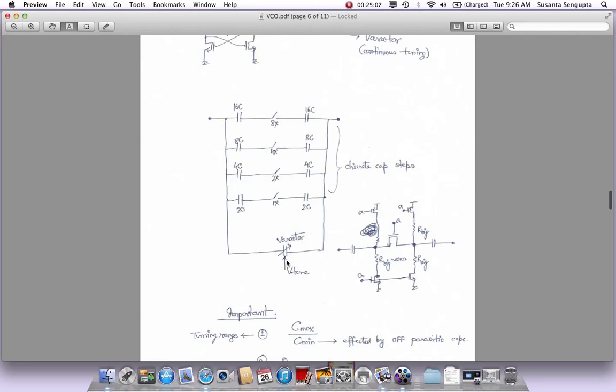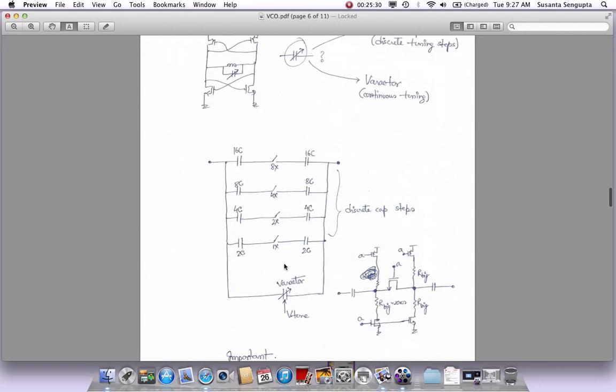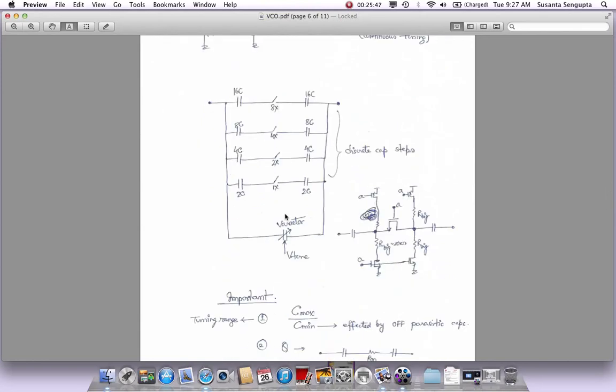Okay, so its input is a tuning voltage, and with that it will provide a continuous tuning within that discrete setting of the frequency that we have. So between discrete steps and continuous tuning, we can cover a pretty wide range of the VCO, and this is how we do tuning. It's not just continuous. You don't put a big varactor there to tune it, because there are reasons for it, and I'll show you why we don't do it, because the kV will be too high. It will have problems with loop dynamics and all that. But this is how we actually implement the tuning of these oscillators.